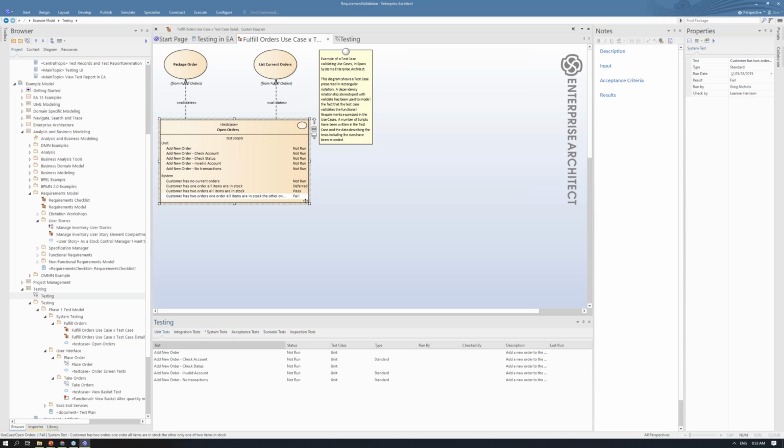It's so easy. As the requirements change, the change will again form a new test for a system or a functionality, so you can import a change as a test case as well. You can import the requirement as a test case. Just say import element requirements, and then choose what type of test you want to import it as. If there are any requirements that are traceable, for example, if this test case traces to a particular change, you can right click and import directly into this test case whatever change has been proposed and approved to go on. You can add it as a test case here. Hope that makes sense. All right.